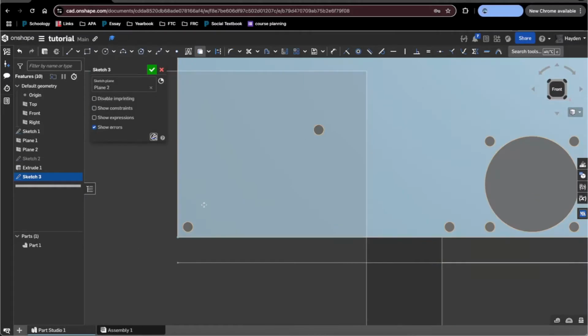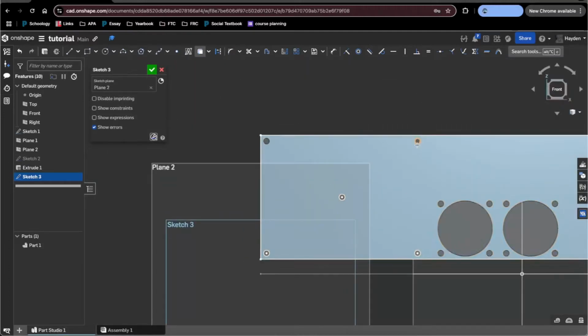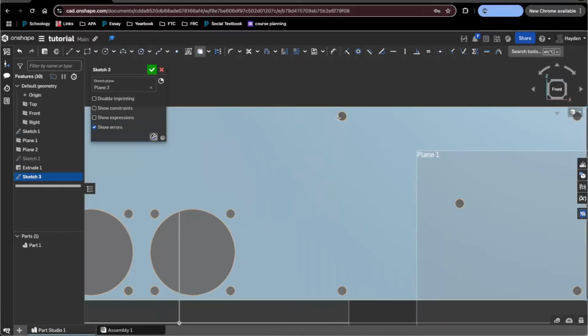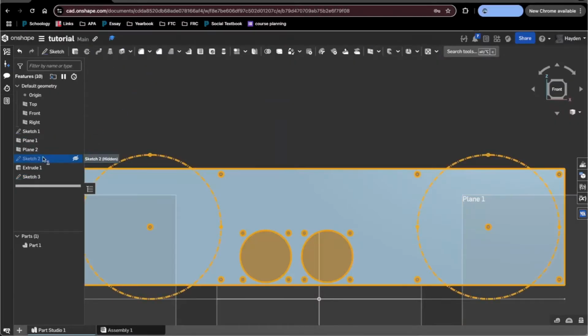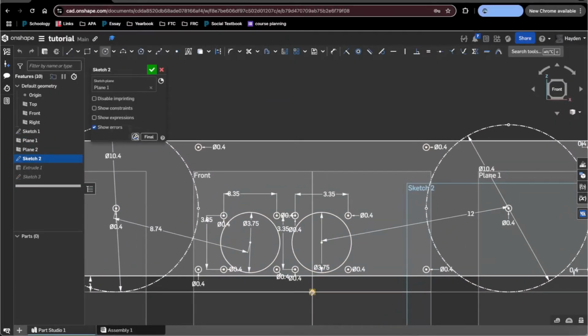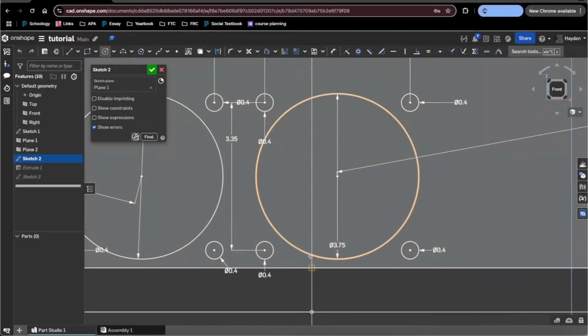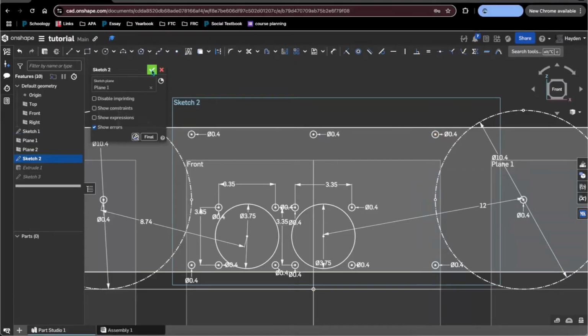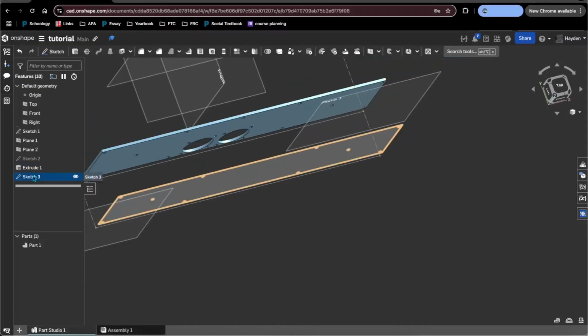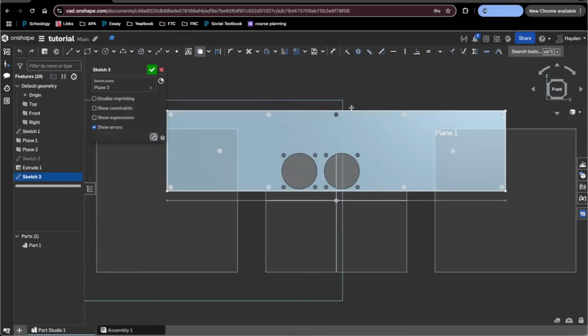What we're going to do is we're going to click on all the screw holes except for the motor ones. So this one, this one, this one, this one, this one, and all of the others for obvious reasons. What you can also do in your parallel plate drivetrain for extra strength is, in this case, we would have a screw hole that's right here, but obviously the motor doesn't allow for that. So we're going to put one up top, horizontally aligned with these. We're going to put a standoff here. Now, just going to project that one.